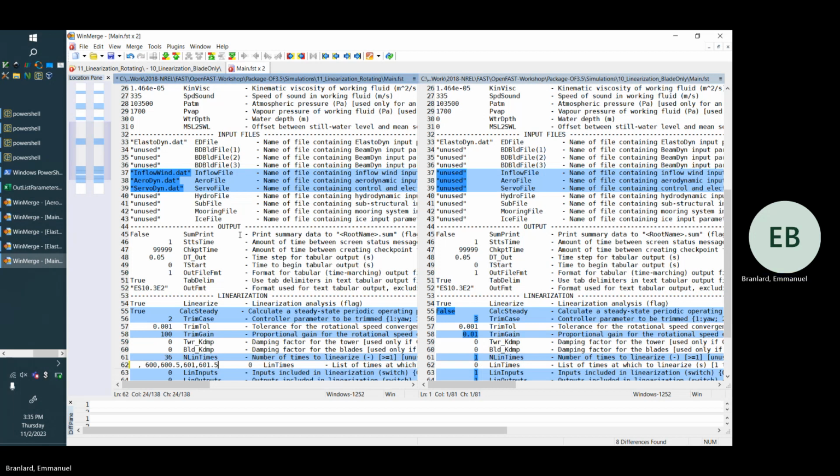Is that what I said, or because that's true? Yeah, sorry. What did you say? Yeah. No, I think Jason mentioned that. Okay, yeah. So OpenFAST is going to complain if you start to use an option like turbulent wind. OpenFAST will tell you no, you can't do that. You use wave kinematics, OpenFAST is going, no, we want a fixed steady still water.